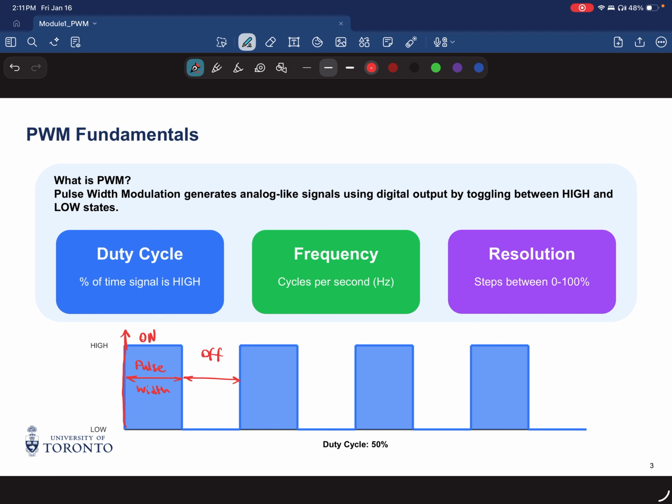So in a way, it's just like blinking an LED, but we set the pin high, and then we keep it there by introducing some amount of delay, let's say T1, and then after that we set the pin low, and then we keep it low for another amount of time, let's say T2.